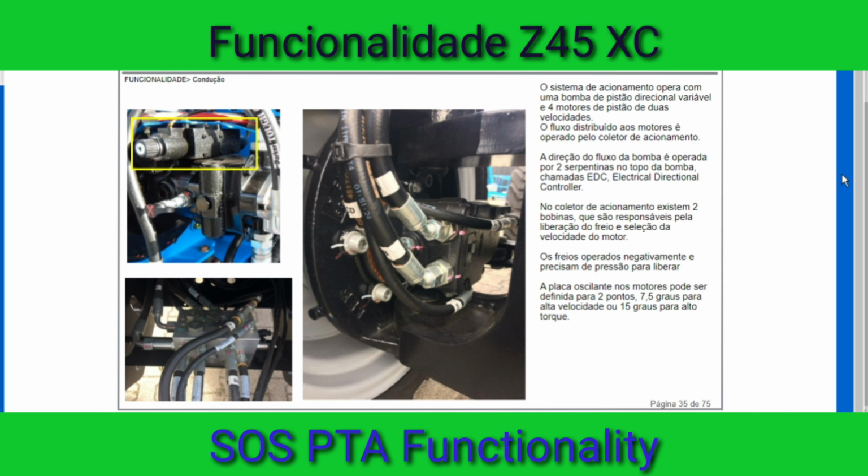The brakes are negative operated and need pressure to release. The swash plate in the motors can be set to 2 points, 7.5 degrees for high speed or 15 degrees for high torque.